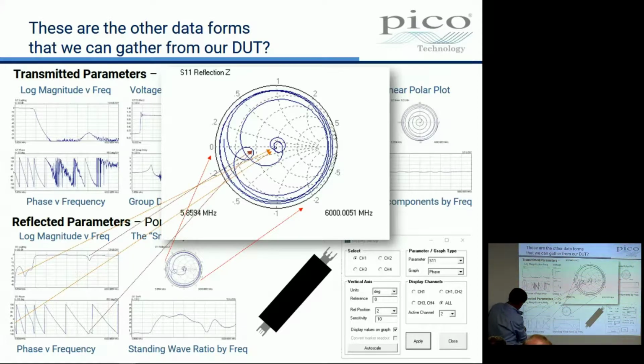And we can start at these 2 points here. This is quite small, this is minus 20 odd dB, quite small, and a little bit off in phase, and it maps, here you are, pretty close to the center of the Smith chart. So I said, well, minus 20, that's a pretty good match. The center of the Smith chart is good match. Yeah? And then as we slide along in frequency, you can see this magnitude comes up and down, but it's still quite small. This is a log scale, don't forget, so these are quite small movements actually.